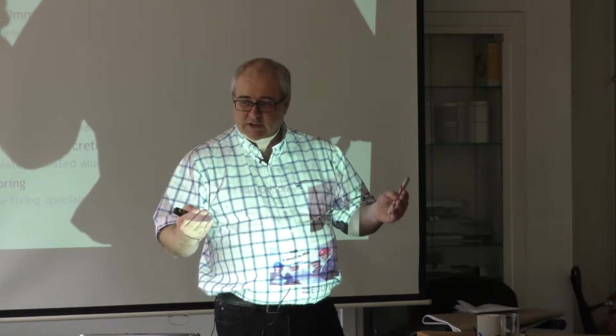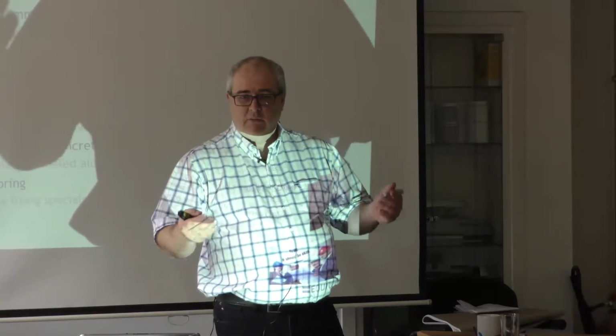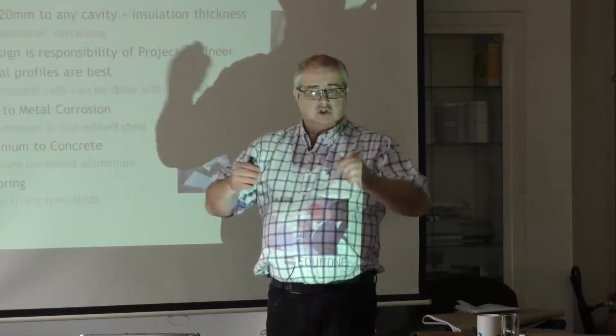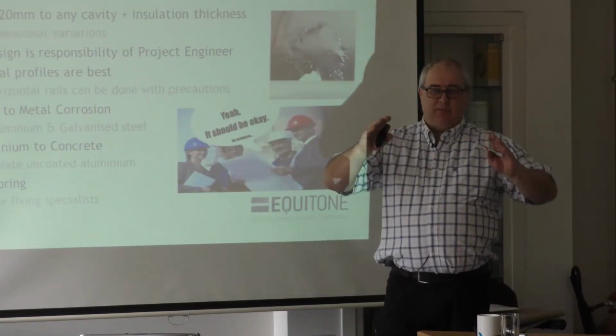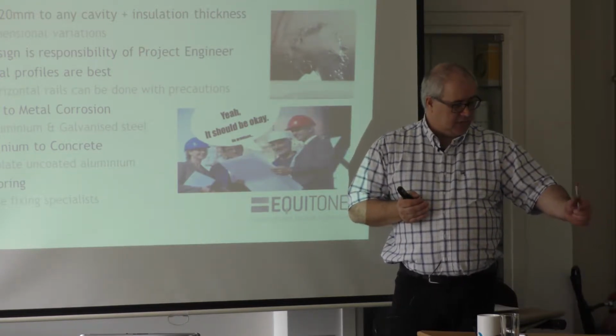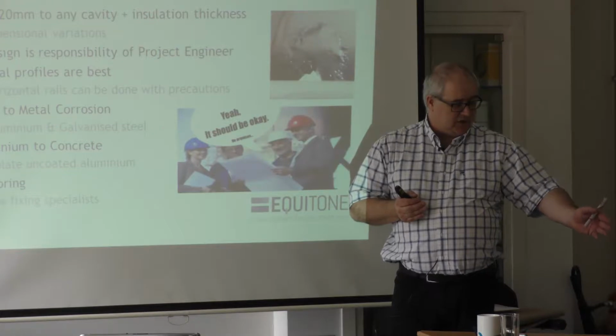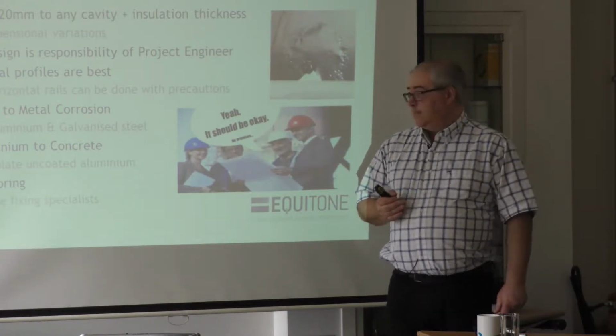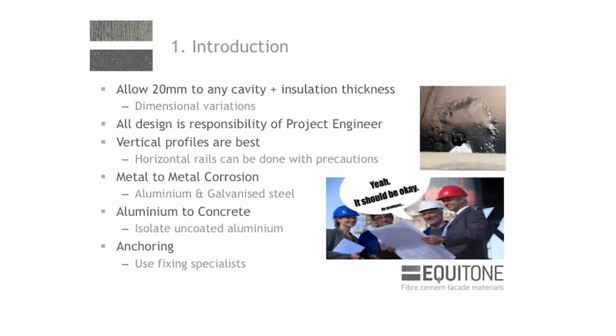But what I would always say is that you get that signed off by the engineer on the project to do that. Yeah? Because there's always a little other calculation in place. For instance, in the south of France, you also have to look after the seismic stuff on the calculations and things like that, which actually tightens up some of the fixings, okay? So be careful about that.